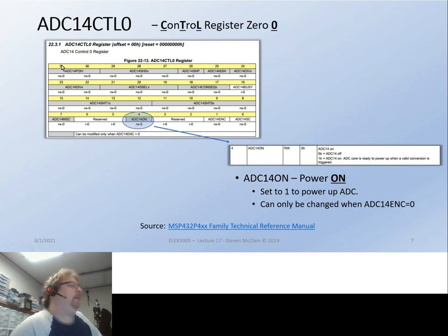Okay, well, if you look at these yellow bands, that's your bit number, right? So this is the lowest bit, this is the highest bit, and then these gray bars are the function. And then you see under here it says RW-0, RW-0. Read write, or set to 0. Read write says you can read it and write it, whereas if you look at this busy flag, it's just got an R. So you can't write. Doesn't matter what you write there, but when you read it, you're going to read it. Same with a couple down here. You can write anything you want here, but every time you read it, it's going to read a 0. That's all you get.